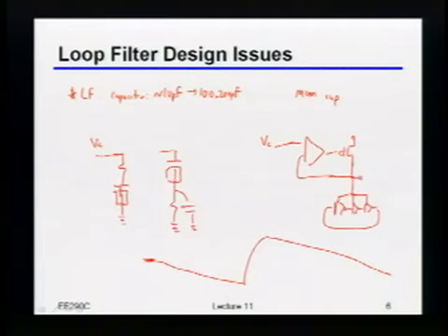Can you inject current back to the node to cancel out? Okay, so there are at least one or two papers that I know of that tried to do that. The trick is that when you try to inject some current back to cancel it, that usually involves having another integration to figure out what's the right amount of current to inject in the first place, right? So then the question becomes, how do you build that integration?